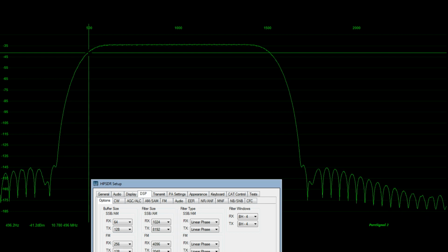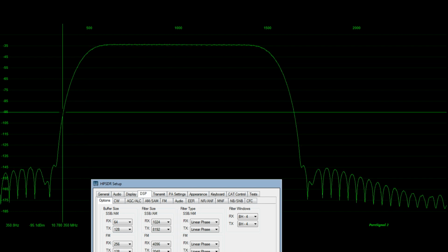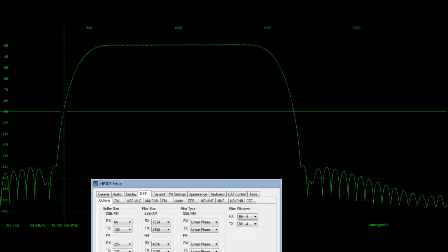And since our 0 dB reference is close to minus 35 dB, that means 60 dB down from that is minus 95 dB. So I'll go ahead and do a crosshair measurement here, get the crosshairs to about minus 95, which is close to there. And the frequency is reading in hertz, which is close to 356. I'll just round that since it's by hand.